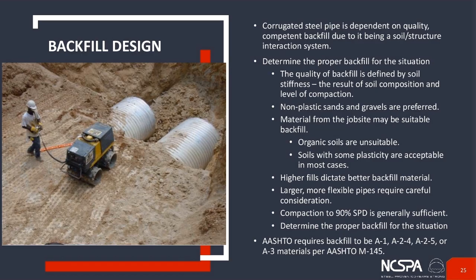But every installation is pretty much unique. So you want to look at it and you want to determine the proper backfill for every single situation. And your backfill is actually defined by the soil stiffness or the quality of it. And that's a result of the composition of that soil and the level of compaction that you can get into it. Non-plastic sands and gravels are typically preferred.